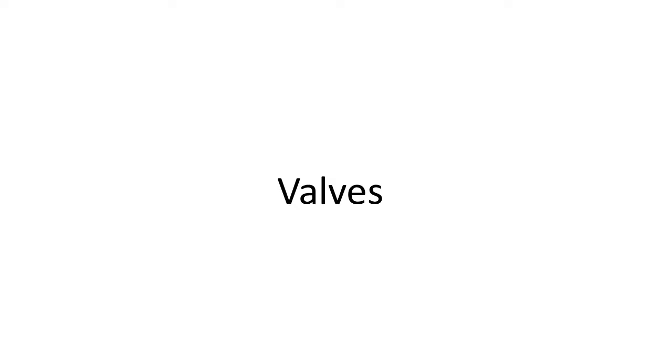The valves can be ordered either at NPT, which is National Pipe Thread, to join with threaded pipe. They can be sweat connections, which is another term, as we know, for solder connections, or they can be connected by a flange that utilizes bolts.